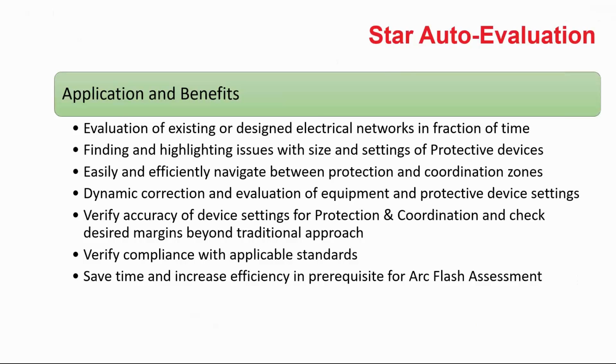And the fruit of this application or this feature or this powerful tool would be increased efficiency in doing protection and coordination study, meaning saving time, especially in larger projects. And as you know, protection and coordination study is the prerequisite for doing any arc flash assessment. So it would help you a lot.